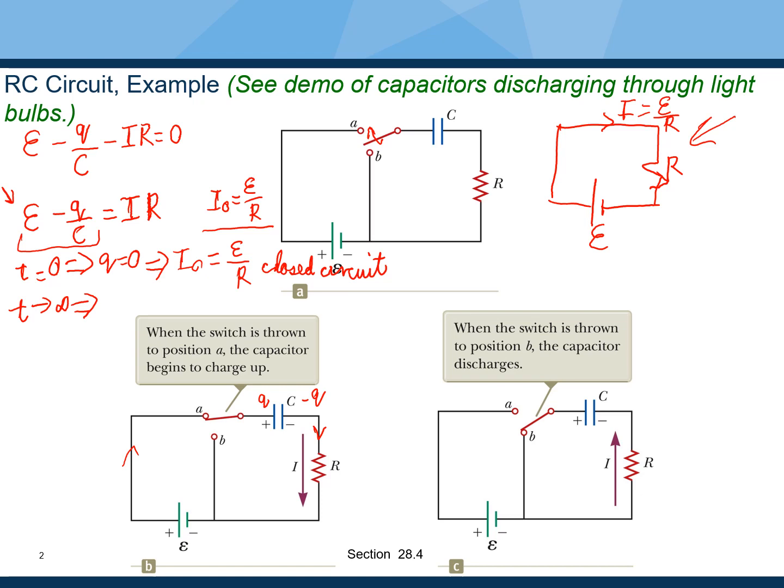So this tells us that at a much later time, Q actually becomes equal to the capacitance C times the EMF of the battery itself. And when that happens, the voltage across the capacitor exactly balances off the voltage across the battery. And when that happens, there's no further voltage drop available, so there's no further voltage available to drive the current through the resistor in this fashion.